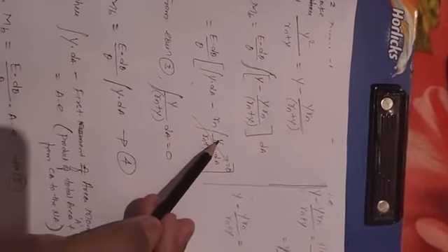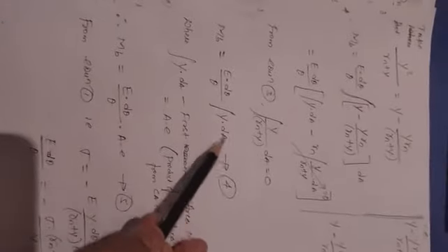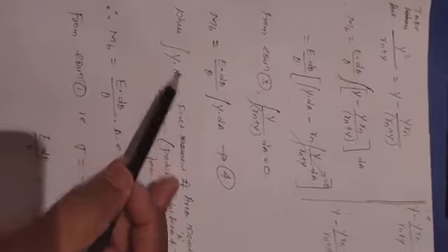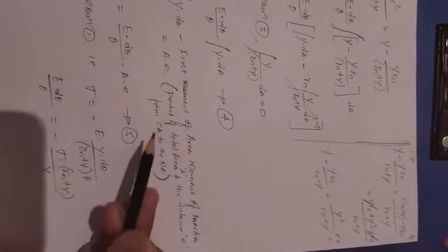As you know, from equation 3, the integral of y divided by Rn plus y dA is equal to 0. The remaining term is what we get. Now what is the interesting point here? Integral of y into dA. What does the integral of y into dA mean? dA is area, into distance. That gives the first area moment. The first area moment is the area of the section into the eccentricity, the product of total area and the distance between the central axis and neutral axis. Then substitute here, that gives the equation for the bending moment.